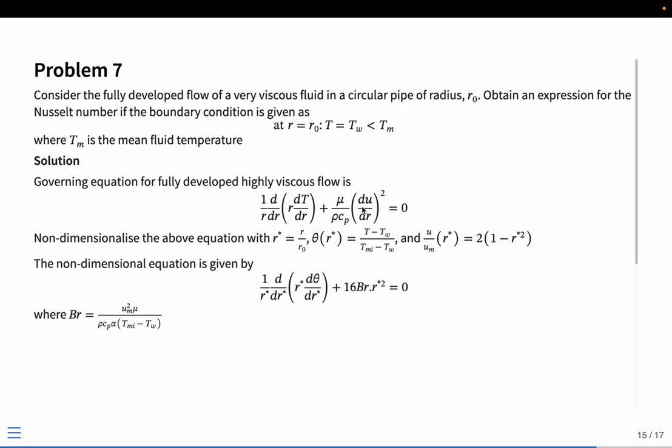Or, to put it in other words, you can say that the viscosity is so high that compared to the viscosity term, the other term, which is just the advection term, is very small. The actual velocities are very small, but the velocity gradients are too high. So you can have very small pipes with high velocities, where the velocity gradient is significant compared to the actual velocity, or when the viscosity of the fluid is very high, so that this generation is too high compared to the advection term. Or to put it intuitively, the rate at which heat is being generated because of viscosity is too high compared to the rate at which it is being convected away. That is what this Brinkman number means.